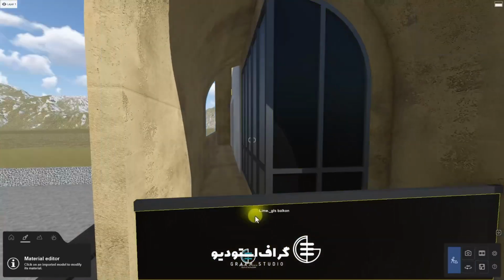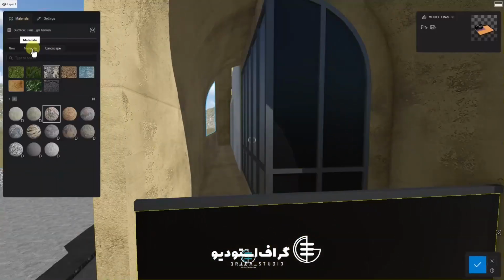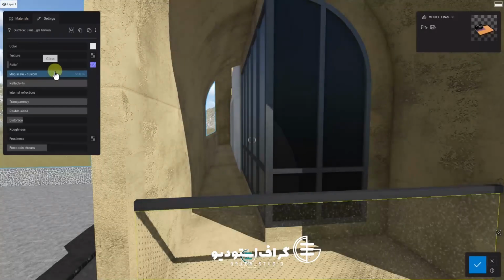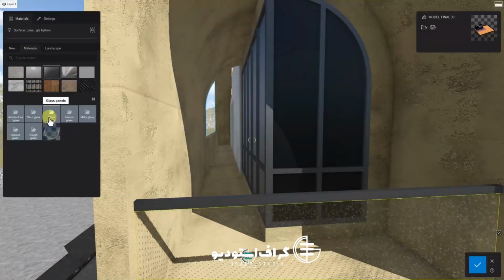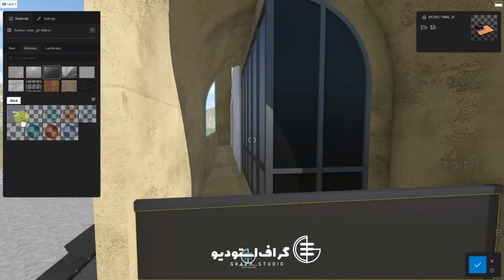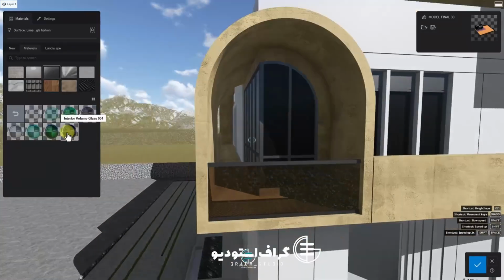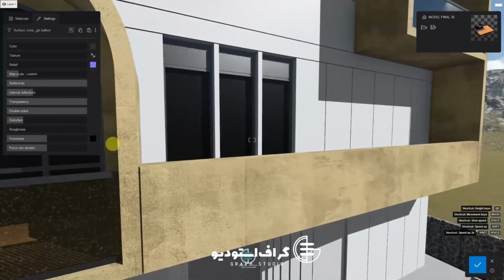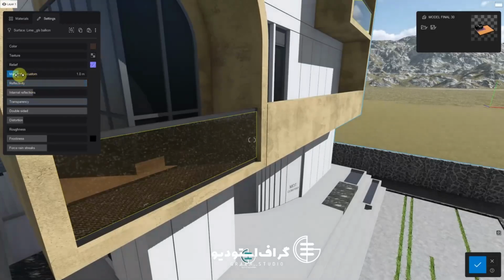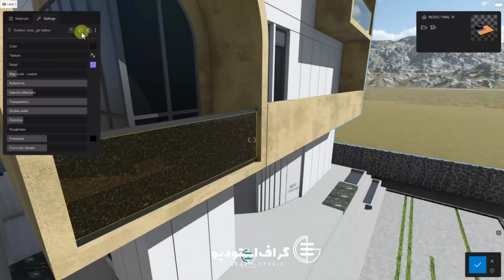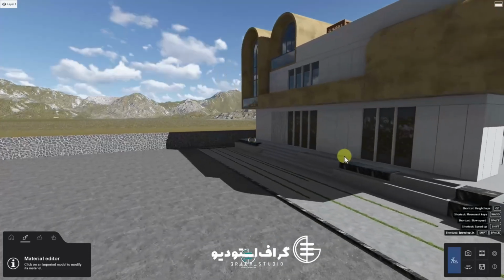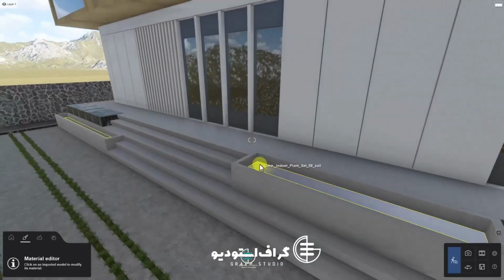I think we should use black stone. I think this one is suitable. You see how well Lumion's excellent archive supports us. If you see anything you don't like, find its texture and PBR maps, and set its properties using the new standard option yourself. Now you know we need rotation. I can adjust its twist to a certain way. This is good now. If it doesn't cause problems from the top, no, this is fine, because it's a ready-made material, and its settings are already okay.